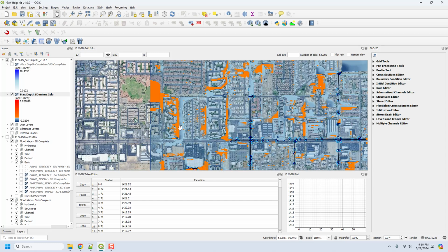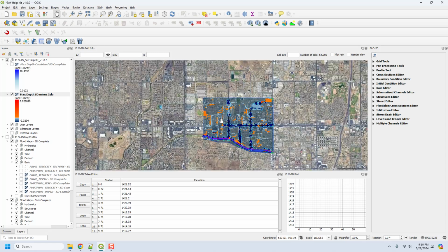Interesting thing also is that in this one we have higher depths on this side. Oh yeah, that makes sense because that water is getting out of here and kind of running down in this area. So there must be a path to get that water back over here and to let it run downstream. Interesting. This all shouldn't be flooded because this is a huge basin, but it's all cut in half by the edge of our project. Not important, just interesting. All right, so that's your depth or raster analysis tool,